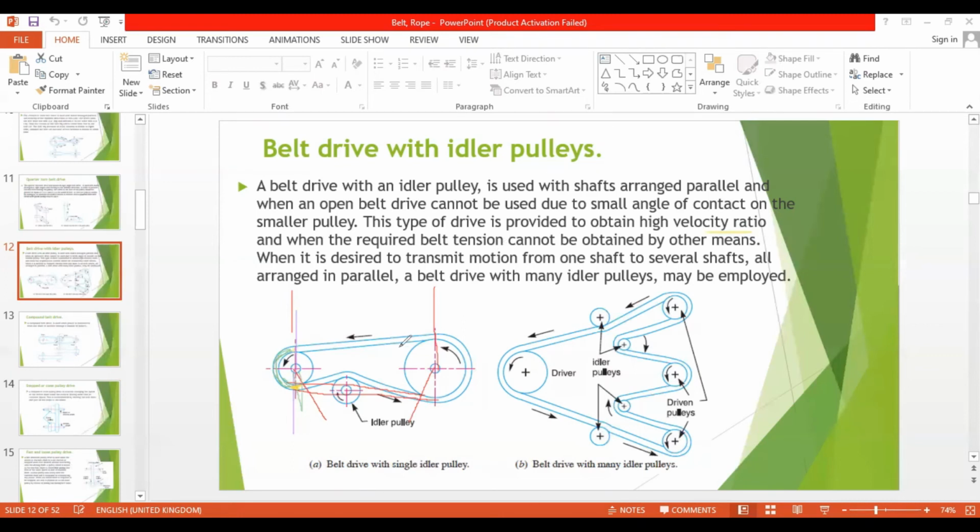There's one more thing. If this belt, with time, has increased in length, it may slide over the pulley, because we can't change the distance between the pulley and the shaft several times. With time the belt could be lengthened, and when you use the belt here, it may not be able to produce the same tension.